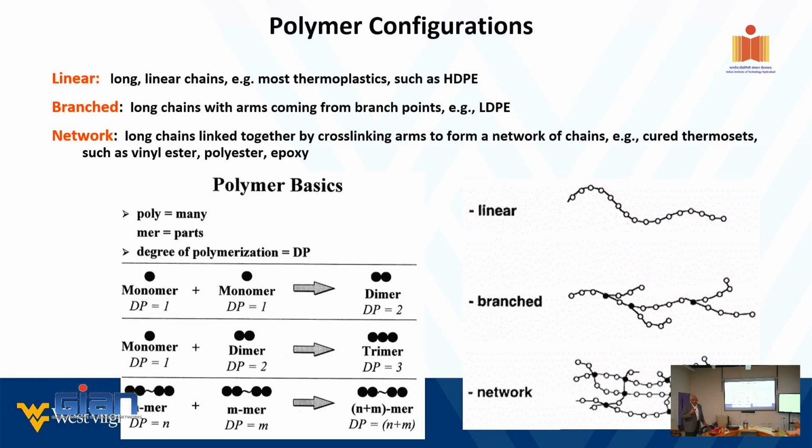So that is another additive. We have the ASTM procedures to establish how much UV I need, how many days I want to expose, at what level I want to expose. All these are built into your ASTM standards. All right, so I broad brushed it again. I'll get to it if you need me to.